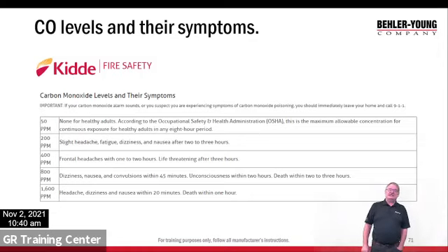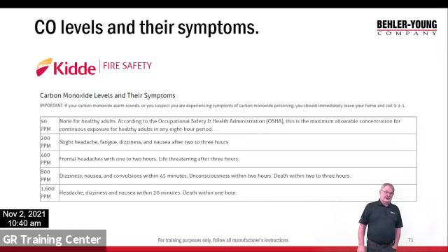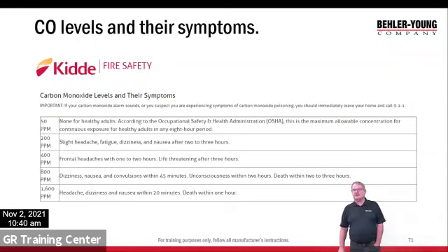Slight headache, fatigue, dizziness, nausea after 2 to 3 hours. Right? After 200 parts per million. 400 parts per million, frontal headache within 1 to 2 hours, life-threatening after 3 hours. Okay, 800 parts per million, dizziness, nausea, convulsion after 45 minutes, death within 2 to 3 hours.